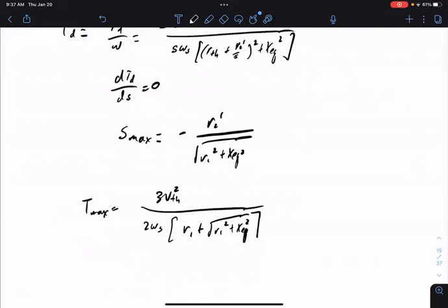Okay? So given the setup of the connection to the grid and the reactance, there is a maximum torque you can develop, right? You can deliver. So again, it's not that the more wind blows, the more torque you can get. There's a max given the generator type. So if you have more wind than this, then again you have some problem. Okay, so this is the maximum torque we have.